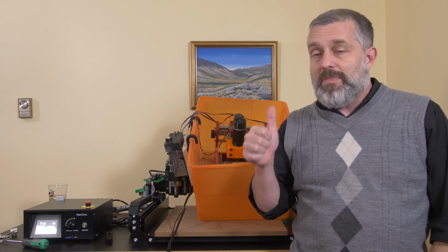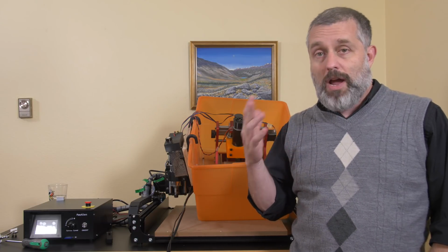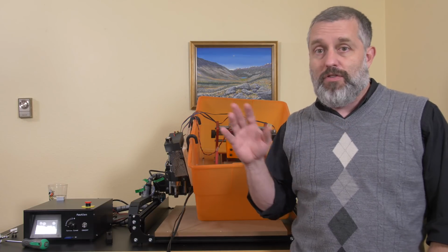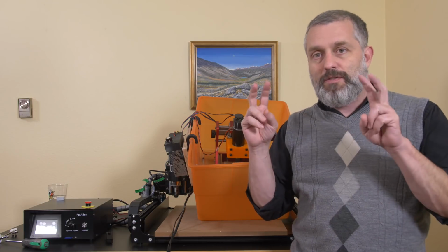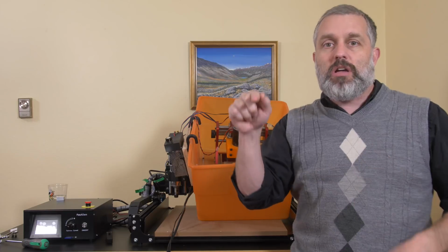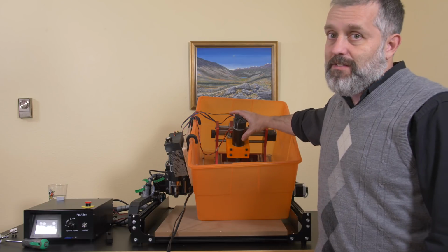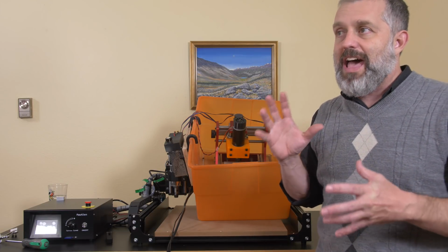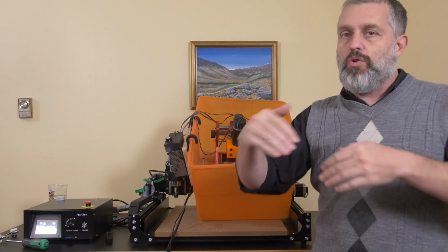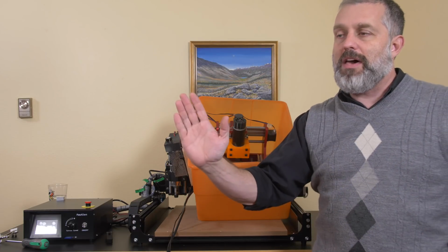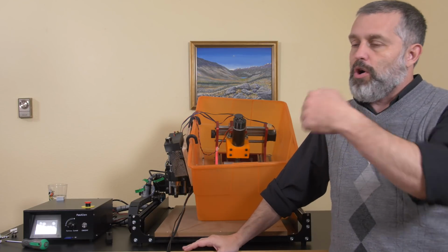First of all, even that professional level toolpath generator that I'm using, which is RhinoCam, is an amazing, fantastic program. If you use Rhino, definitely get that. It's worth the money. But this adaptive toolpath that does the sweeping action that I was talking about, I really need that to compensate for the lack of rigidity and stiffness in this machine. I just don't have the oomph. I have the strength, but I don't have the stiffness to push through the metal with that entire face of the bit, even when I'm just doing a very small depth cut. It just doesn't work. I need to be taking smaller bites off.